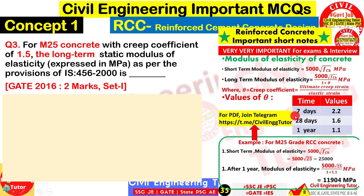If we are asked what will be the long-term modulus of elasticity after 7 days, in that case we will use theta equal to 2.2, but after 28 days it is 1.6, and for 1 year it will be 1.1. A sample calculation I have already posted on my Instagram page, so if you are following that page, you must have seen this calculation earlier. But in this case, they have asked for M25 concrete and the creep coefficient is already given, so we do not have to use these values here.